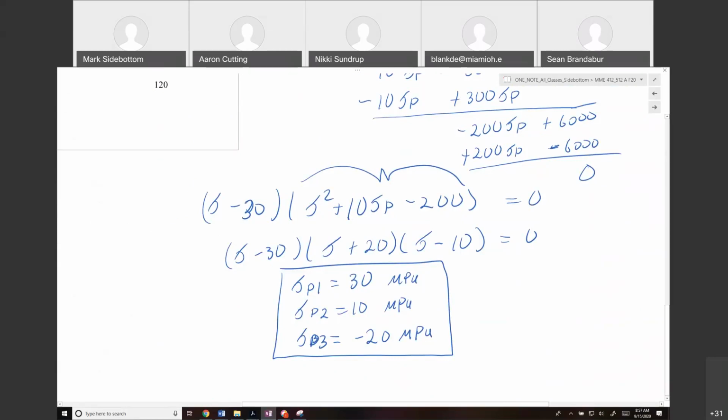It's like a property that doesn't change when you do the stress transformation. So you can do it before and after your stress transformation to make sure you didn't mess anything up, right? That's correct, Greg. That's absolutely correct.